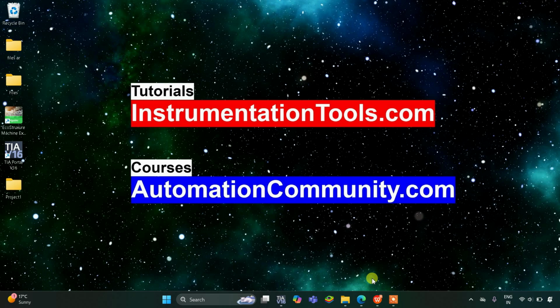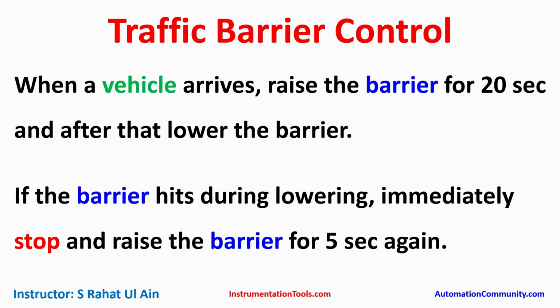Today in this video we are going to discuss another example which will be about traffic barrier control. So let's look at the example first. Traffic barrier control. When a vehicle arrives, raise the barrier for 20 seconds and after that lower the barrier. If the barrier hits during lowering, immediately stop and raise the barrier for 5 seconds again.